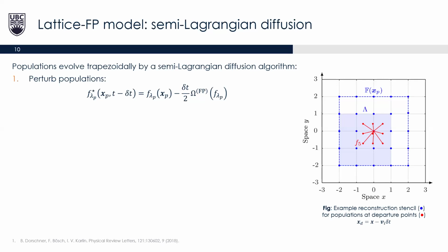And then particles on demand uses this crucial step of transforming the populations in the stencil to the same inertial reference frame as the current monitoring point that you're trying to update. And so you construct a transformation matrix that makes sure that your moments are conserved in either reference frame.